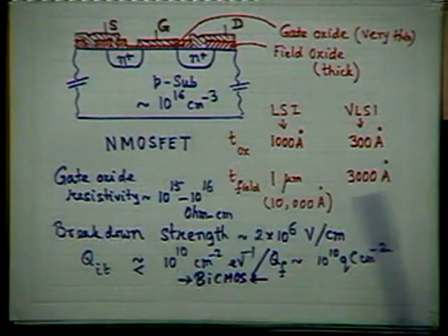Can you tell me why you would do this unnecessarily? The technology will be very complicated. Implementing both bipolar transistors and MOSFETs on the same chip, where both kinds of devices should have very good, high performance features, is needed. Otherwise, if MOSFETs are much inferior to bipolars, or vice versa, it will be very bad. You have to take some route so that ultimately both kinds of devices are excellent in their performance. In a good BiCMOS, definitely your technology is going to be more complicated.